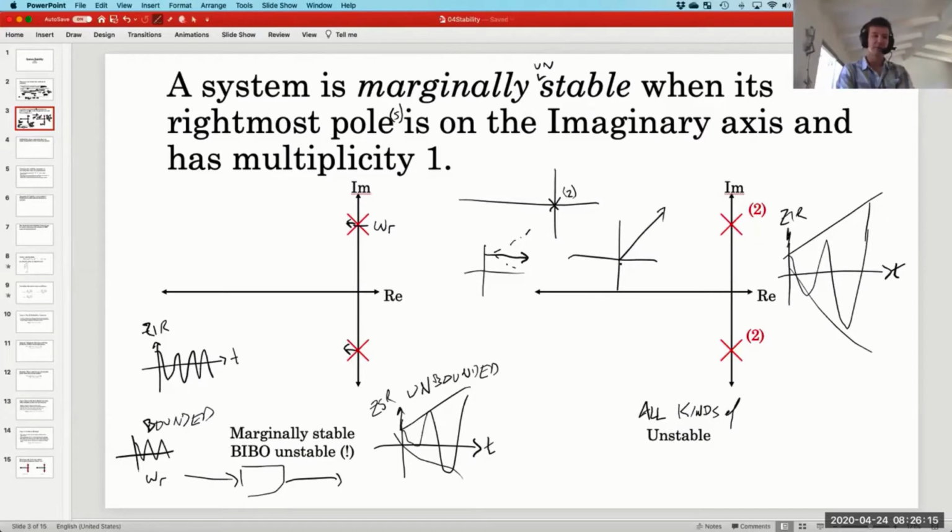Yeah, for sure. I will answer your question, but I want some feedback from you, so to speak. Get it? Feedback. Which poles did we like at the origin in the steady state error? Like, were they the system poles, the closed loop transfer function poles, or were they a subsystem transfer function? Oh, subsystem. Yeah, it was just the forward path transfer function that we liked having integrators in.